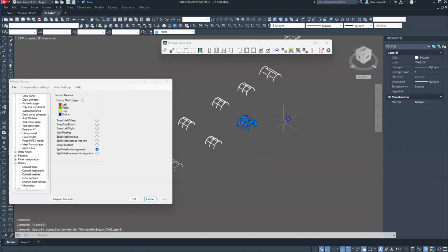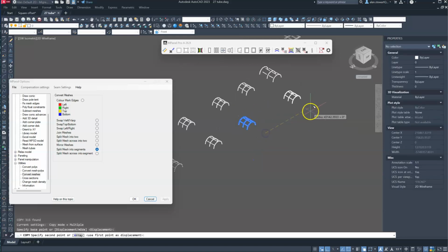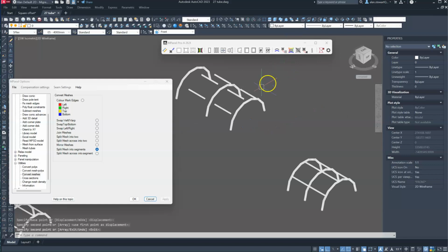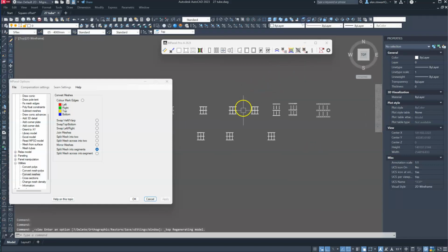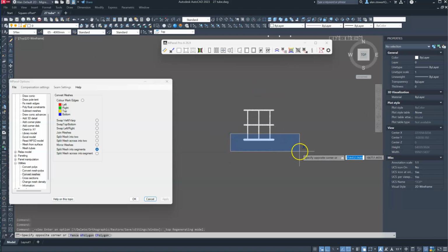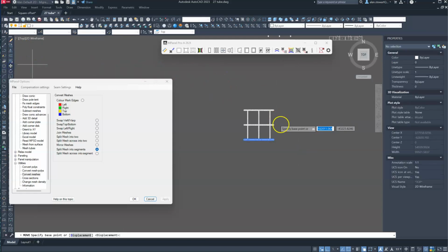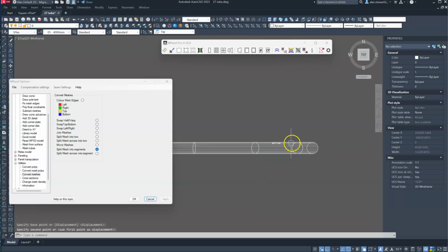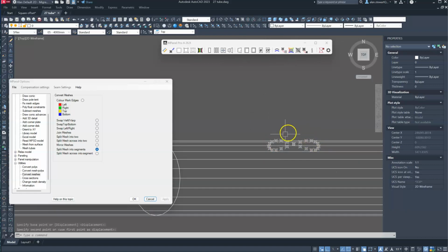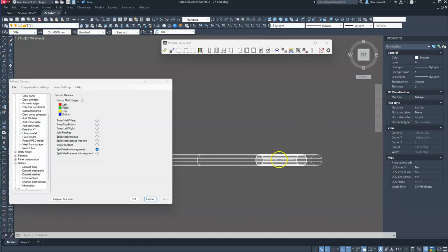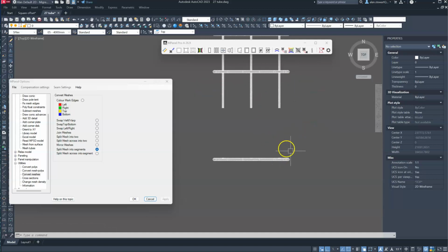Again, I'll take a copy. Now the final step here was to separate the tubes from each other. So I'm selecting all of these elements here and moving them, and you'll see in that selection there are all of these points which represent the connection point where these beams connect to the tubes.